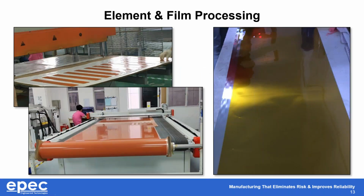Next, once we move forward, we begin making the heater itself. The heaters themselves, we build using a variety of processes. On the right-hand side, this is an etched foil heater before the traces have been etched. This is what the heater looks like in its original unadulterated form. On the left-hand side is silicone film before it's been vulcanized, being cut to shape and processed. Since we are the manufacturer and we're building these completely from scratch, we're able to completely customize the heater with whatever you need for a design, shape, and performance.